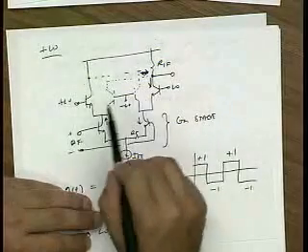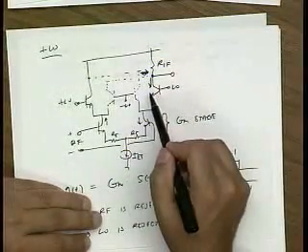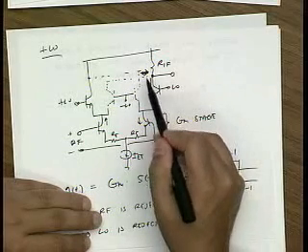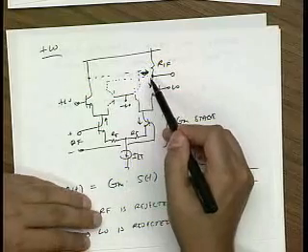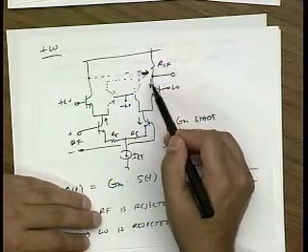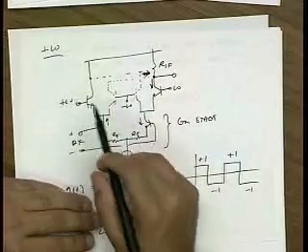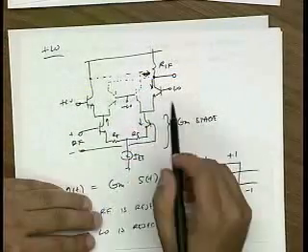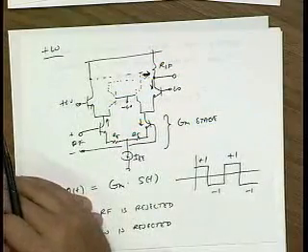So because the noise of each transistor is independent from the noise of the other transistors, these signal currents cancel out, but the noise currents add in quadrature. And so the noise of these two stages adds to the output. So here it's even more important to have a very large swing to try to reject the noise coming from the LO port. Okay.